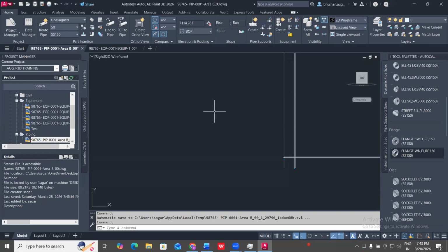This topic is also confusing, because for that you need to have some theoretical knowledge, like the difference between the elbow and a bend. So now I will explain this also. An elbow is a prefabricated fitting. It is manufactured in a factory, right? It comes in standard sizes like 90-degree, 45-degree, and is welded or flanged to the pipe.